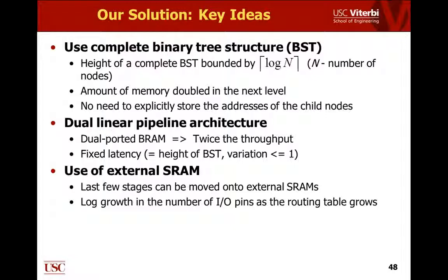The advantage in the complete binary search tree case is that I don't have to explicitly store all the pointers from a particular node to its children. That saves a lot of memory, as well as a lot of power dissipation. In fact, in these applications, most of the power is dissipated in the memory storage. So by using this kind of complete binary search tree structure, we can significantly reduce the amount of power that is dissipated.